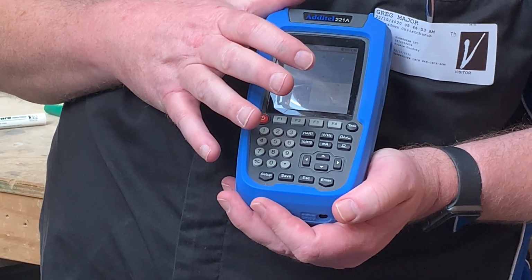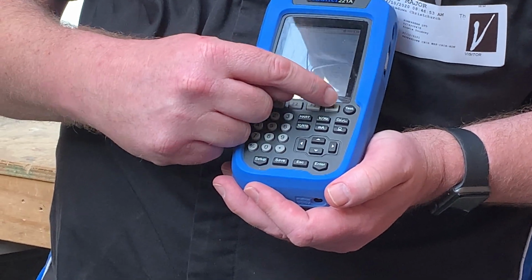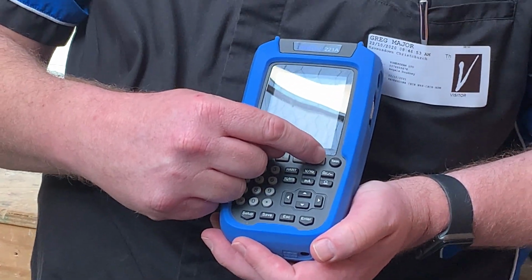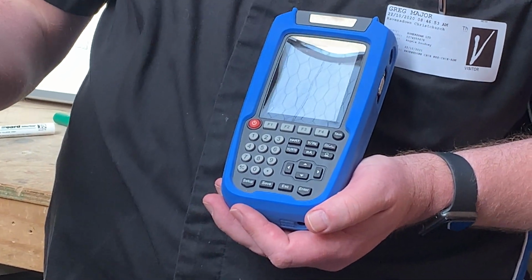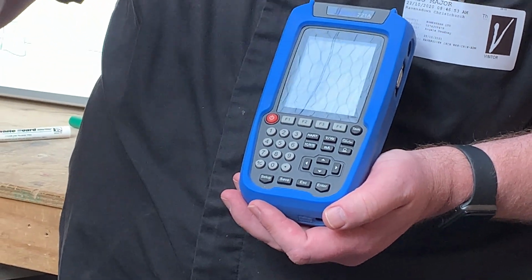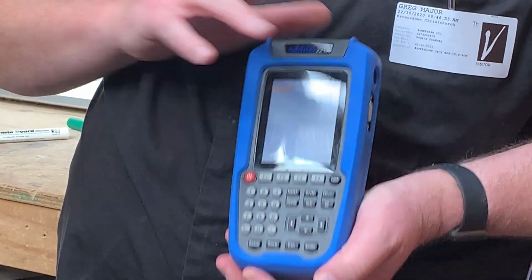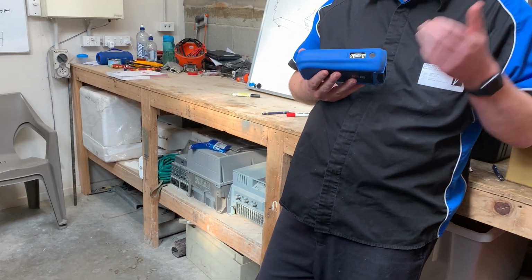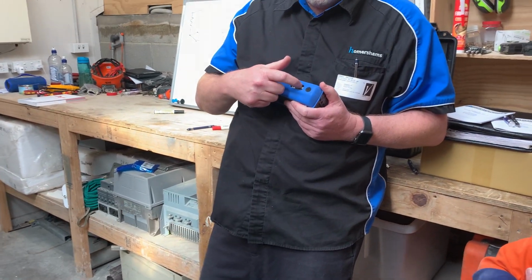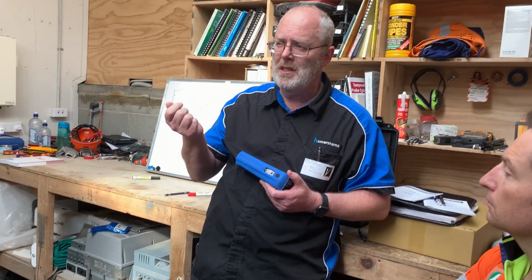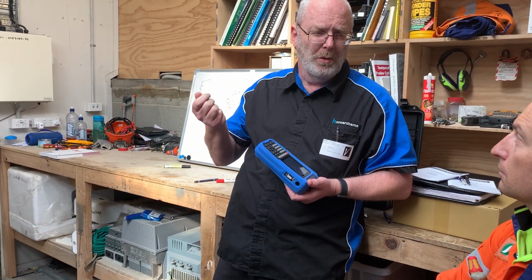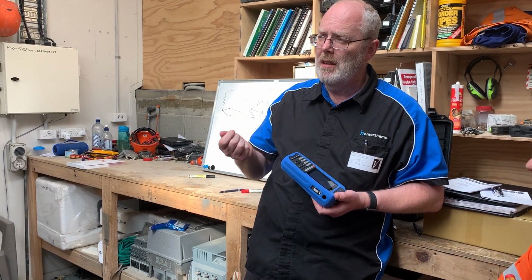This one fails. You could now save that as an as found report, and then the tech could come back to you and say, here's the results. Then you could send them out, do a calibration, do an as left. It doesn't come with it, but if you go down to PB Tech, for example, you can get an RS232 to USB connector for $20. You can actually use it as a full documenting calibrator.